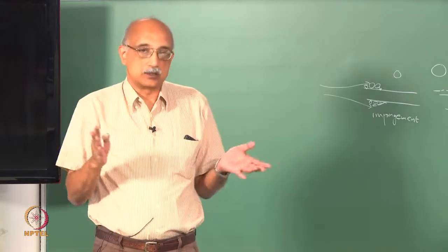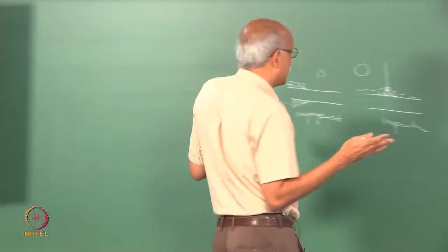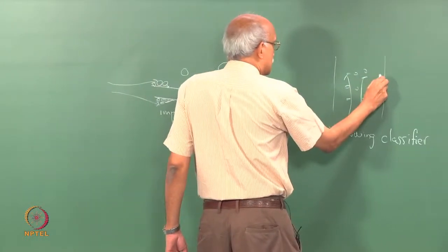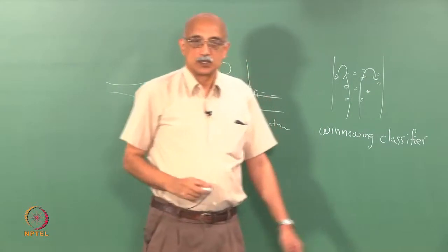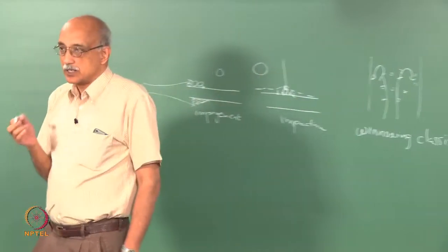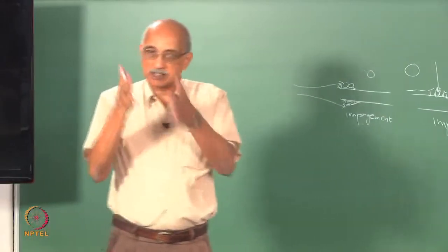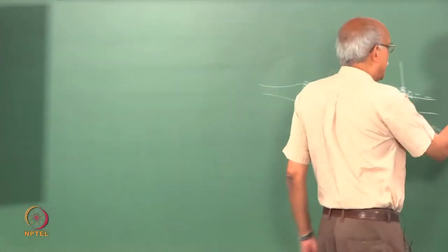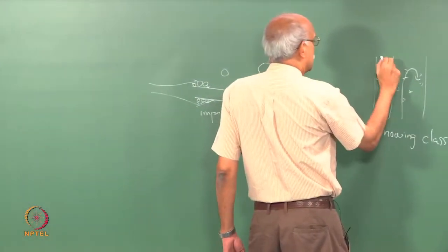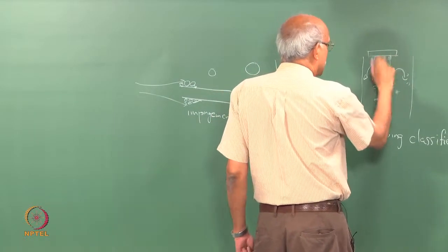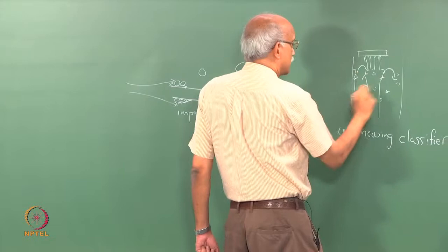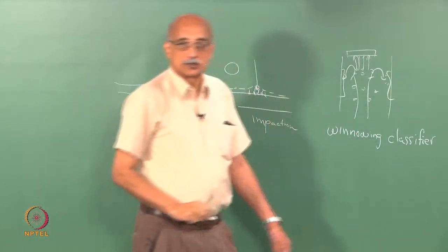The lightest particles will basically behave almost like vapor molecules. So, the smallest particles will get blown to the outer diameters, whereas the largest particles that have more inertia will stay in the center of the chamber. So, if you have a collector here, they are more likely to be collected in this region, whereas the finest particles will collect on the walls.